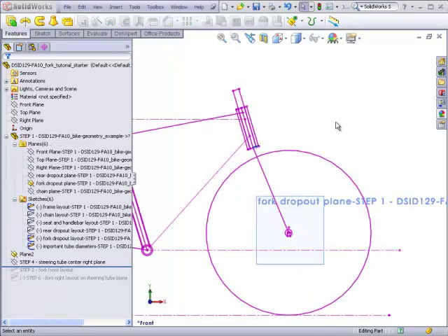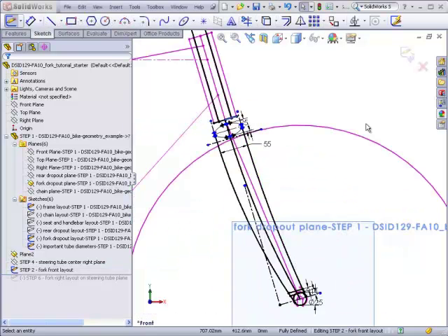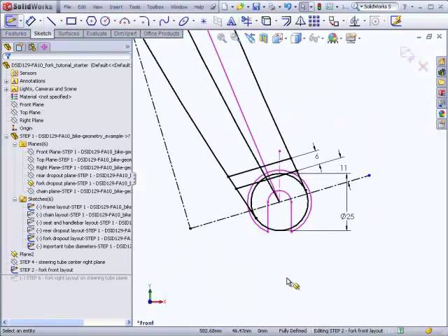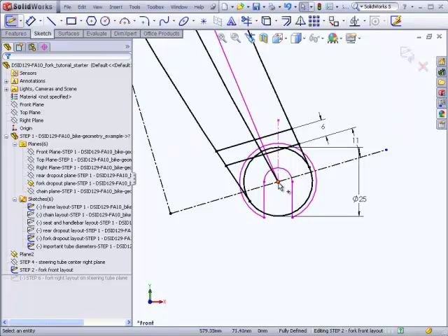Going back to the starter file, I will now show what the sketch looks like for the front layout. Here I've drawn a sketch for a classic bike fork that has a clean sweep from the crown down to the dropout. I've drawn the leading edge, the trailing edge, and a center line that will end up representing both the outside and the inside edge. This line I've drawn is coincident with the axis of the steering tube. This line is perpendicular to it and passes through the center of the dropout.